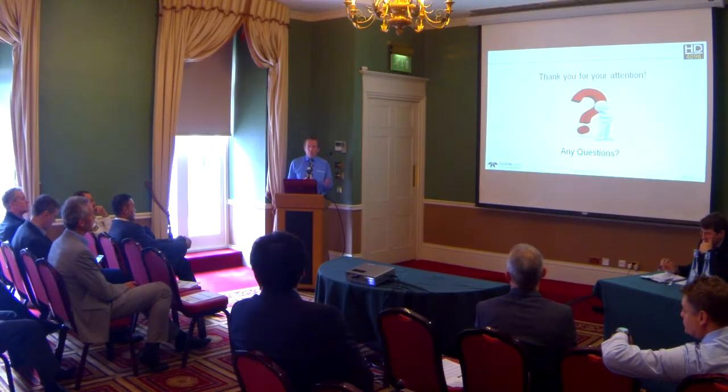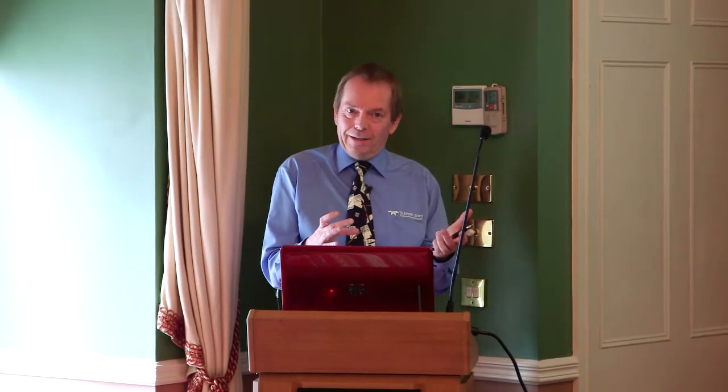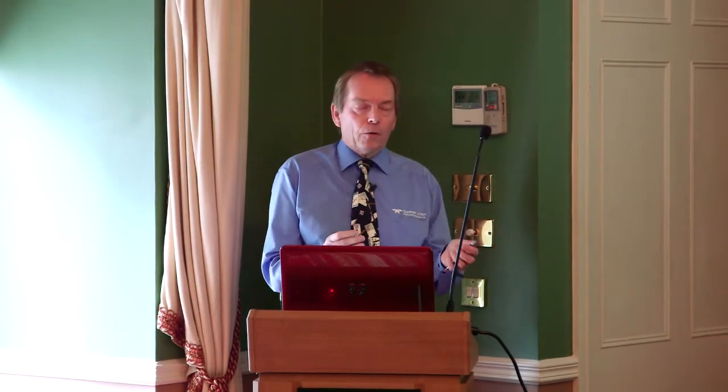Well, if you're doing, for instance, communication links, eye diagrams, those kinds of things, on a high-speed link, we're doing eye diagrams and jitter measurements and those sorts of things today with 8-bit on high-speed links. When you look at those eye diagrams, because it's 8-bit, there is a contribution to the vertical noise of the 8-bit, so you don't get as good an eye diagram as you could if you actually did have 12-bit. We don't have it, but from the other things we've done, we know that we will get more accurate measurements on communication links and things like that.